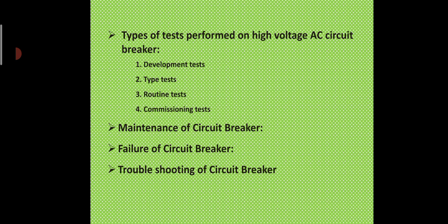Now, maintenance of circuit breakers. In maintenance of oil circuit breaker, there are periodic maintenance inspections in ordinary conditions. During the periodic checkup, internal and external inspections should be done after the fault when the circuit breaker is isolated. Post fault maintenance of circuit breaker covers cleaning, condition of arc control devices, mechanisms, insulation resistance, insulating oils, joints and seals. The steps of maintenance of minimum oil circuit breaker are quarterly, half yearly, and yearly.